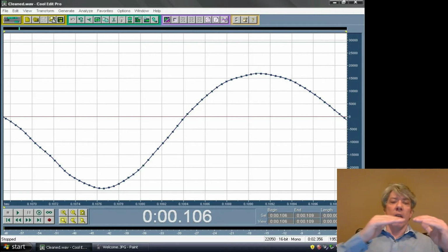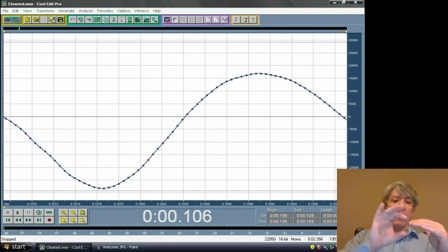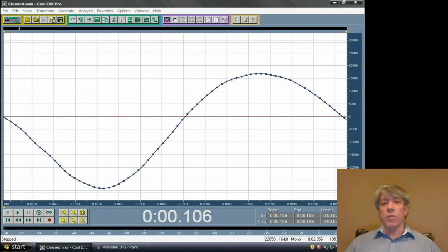Well, if you think about it, the speaker's amplitude is being represented by 0 to 65535. Those are the numbers we have. And as the song volume fades out, the speaker is actually not moving so far anymore, because the farther the speaker moves, the louder it will be. So if the overall variation gets quieter and quieter, the speaker won't be moving as far. Well, we're getting into a region where we don't have as many numbers to represent the speaker's position. And so, as you crank up the analog volume on your player, you're actually amplifying something that doesn't have as high resolution. You can actually hear the scratchiness.